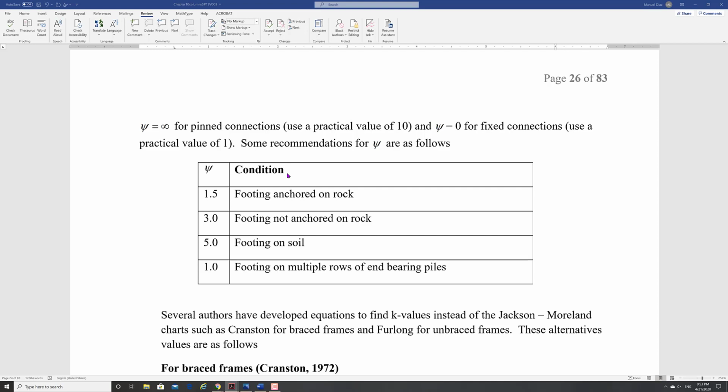So there is no need to panic. You don't have to put in these springs and try to model perfectly. That's ideal, yes, we would like to do that, but doing a pin connection is reasonable. You're very conservative, and you get a good design.